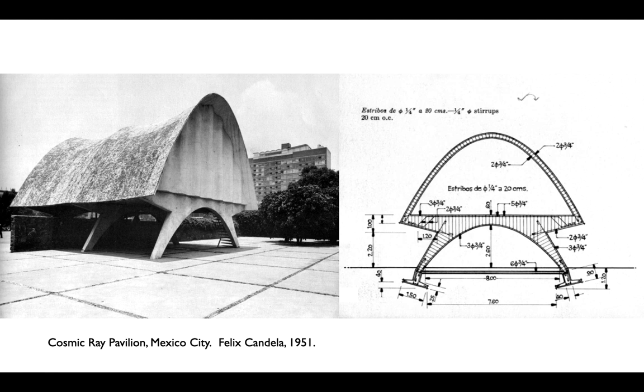But Candela here is beyond simple beam theory because that roof has to be so thin. And so it's not just about the kind of actual distance that the thing is spanning. It's about the fact that he has to resort to a very, very different way of spanning because a simple beam and slab would require too much reinforcing or too much thickness in the concrete. So here I think is a great example of what we might call a short long span, right? A quantitatively small span that nevertheless has difficulties with it that we associate with longer span construction.